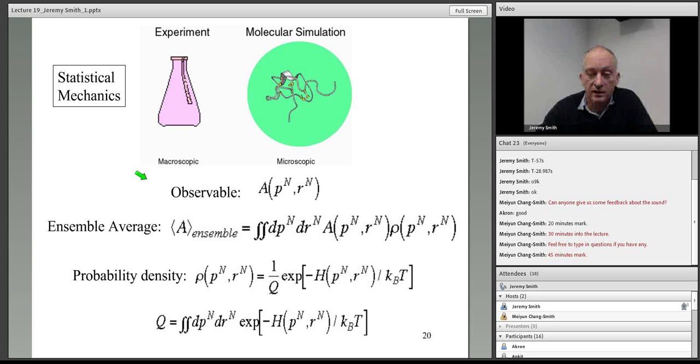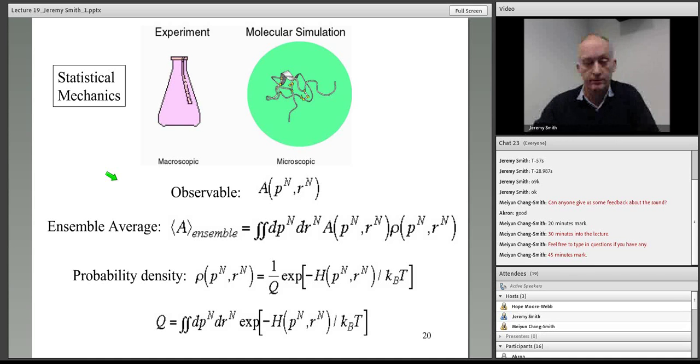We do that, calculate the correlation functions that I showed you before from the simulation, and then you can calculate your scattering densities, your scattering profiles. So there is efficient software to do that. The software that we wrote is called SASIM, and it parallelizes very well on modern-day supercomputers. And you need supercomputers to do calculations of these things from large simulations these days. From small simulations, it's not so important, but from large ones on large systems over long times, you need high-performance computing.